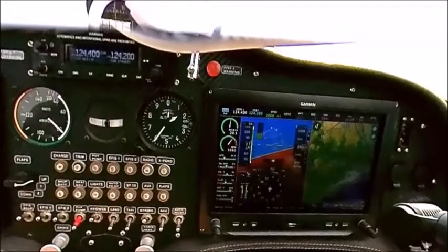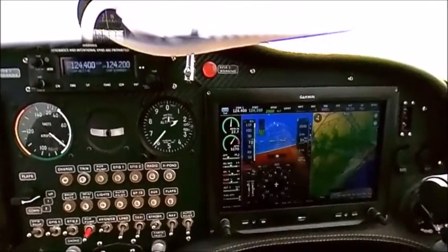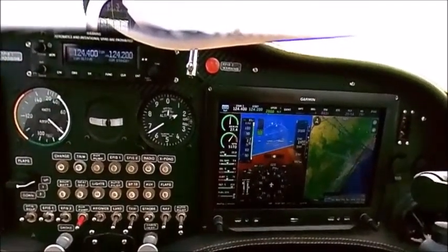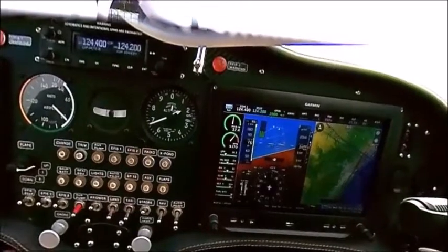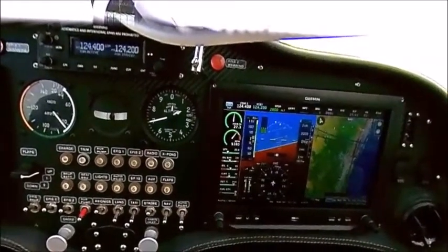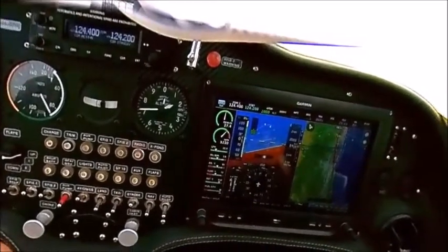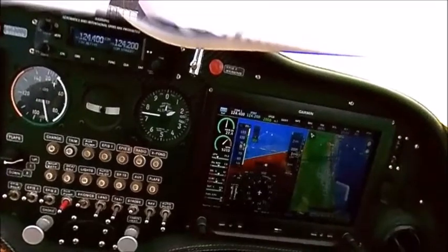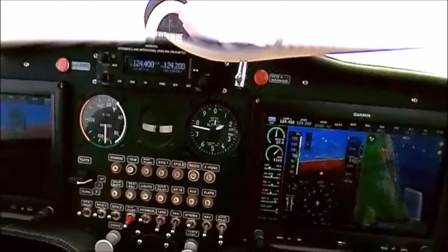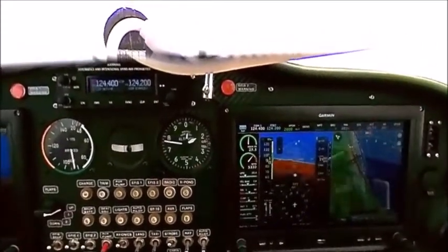While I'm going here at the same RPM or engine speed, I'm making an 80 degree turn, and you will notice that initially the speed is 92 knots, and then it will eventually increase to 110 knots. This just depends on whether we've got a headwind or tailwind. At 92 knots it would be a tailwind, headwind would have been at 110 knots. And obviously the ground speed will be less when you're going in the headwind direction.